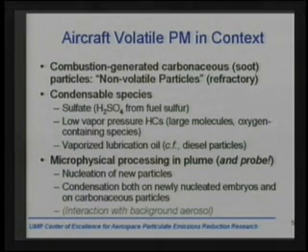As you move downstream, 30, 50 meters, or even further, the condensable species that are emitted come into play, things like sulfate, which arises from the small amount of sulfuric acid caused by the fuel sulfur content. We also have low vapor pressure hydrocarbons associated with the combustion process. That's most prevalent at low powers, but it increases as we go to higher powers. And there's the possibility also of vaporized lubrication oil. All of those can contribute, but they aren't present as particles at the engine exit plane. They only go into the particle phase as we move downstream, and that requires microphysical processing, either in the plume, and that's certainly what we're most interested in, but when you make a measurement, you have to worry about whether it happens in the probe as well.